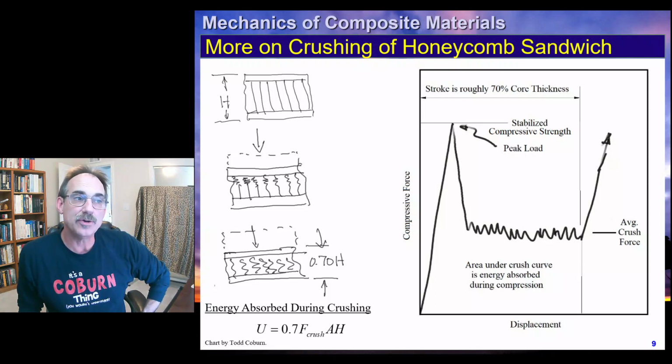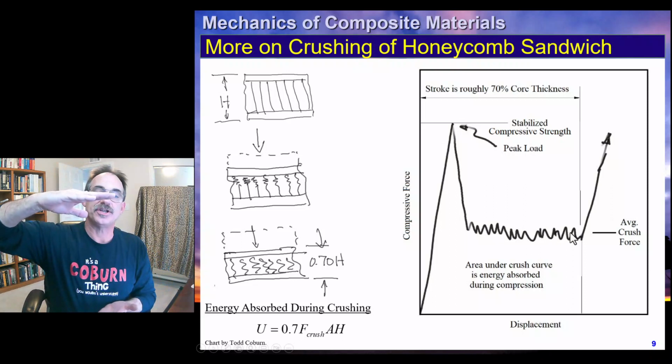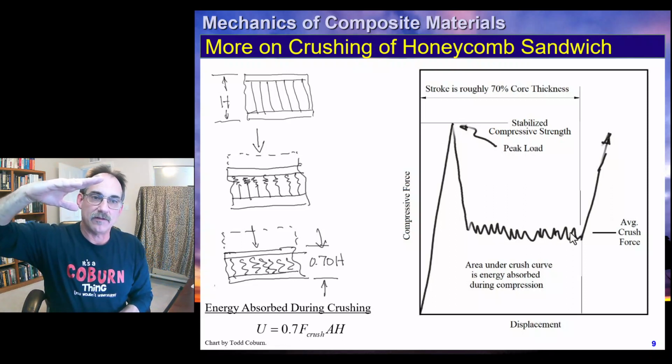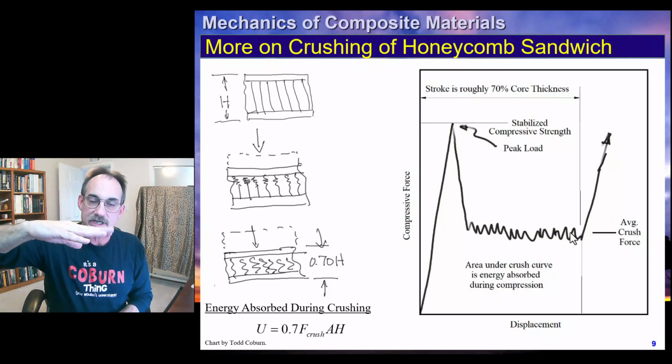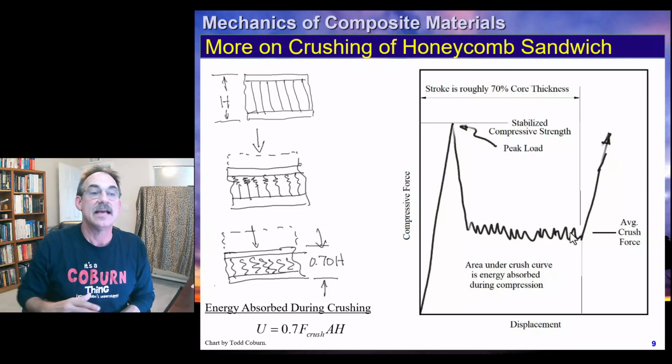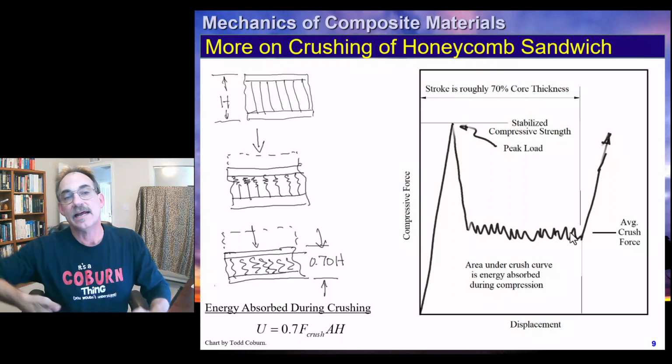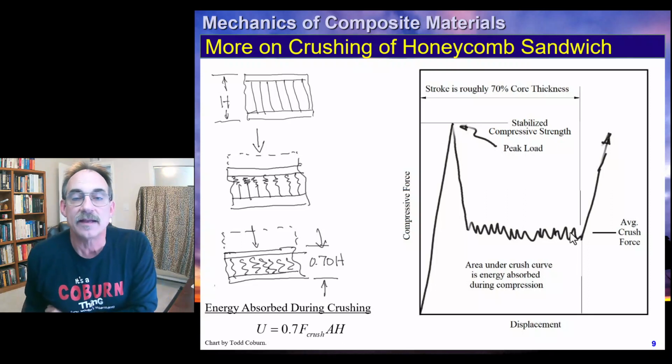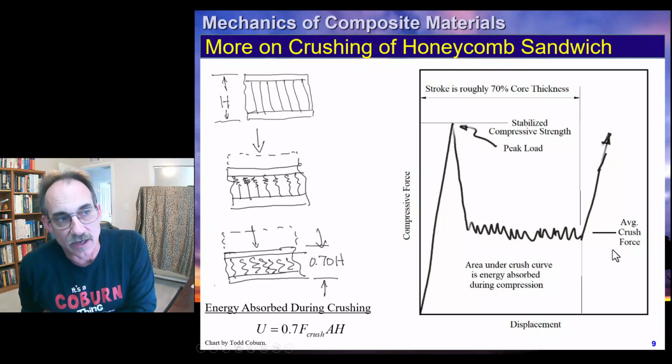When you do, you get a huge load drop. And then you get a nearly even hold of stress as that thing crushes. So you put a certain force on it, and if you're reading the force in your load machine, it'll be basically a constant force as that thing deflects until you get to that solid height, and then your load starts to increase drastically quickly.